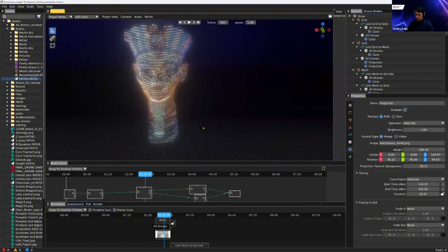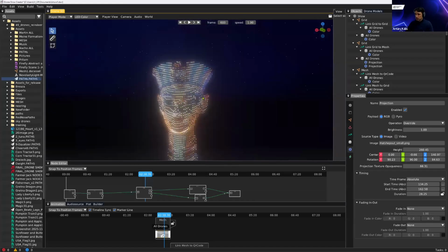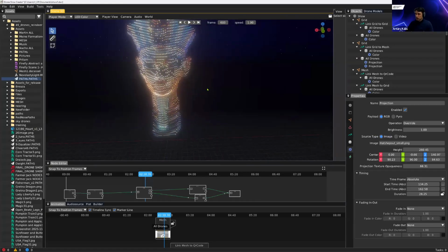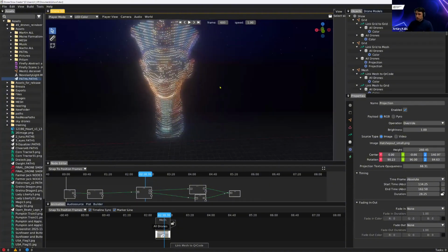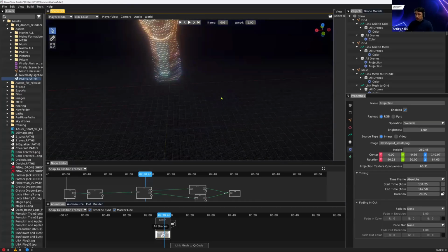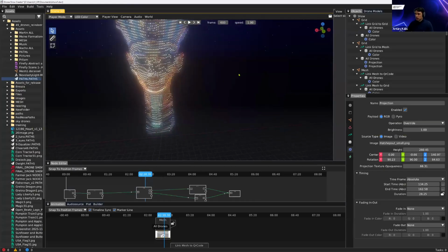Just briefly, to pan the camera, you can hold the middle mouse button. Oh, no, panning, I think it's this one. You need to hold Shift and middle mouse to pan up or down. Then to change the pitch, you just hold the middle mouse button.